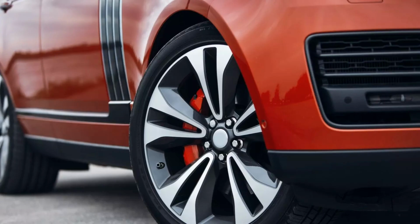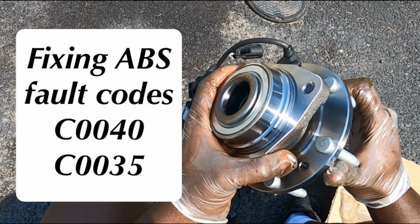ABS code C0040 is a diagnostic trouble code, DTC, indicating a potential malfunction of one of the wheel speed sensors or the sensor circuit. What does fault code C0040 mean? Code C0040 indicates a malfunction in the right front wheel speed sensor circuit. This code appears when the ABS module detects a problem with the right front wheel speed sensor or its circuit.